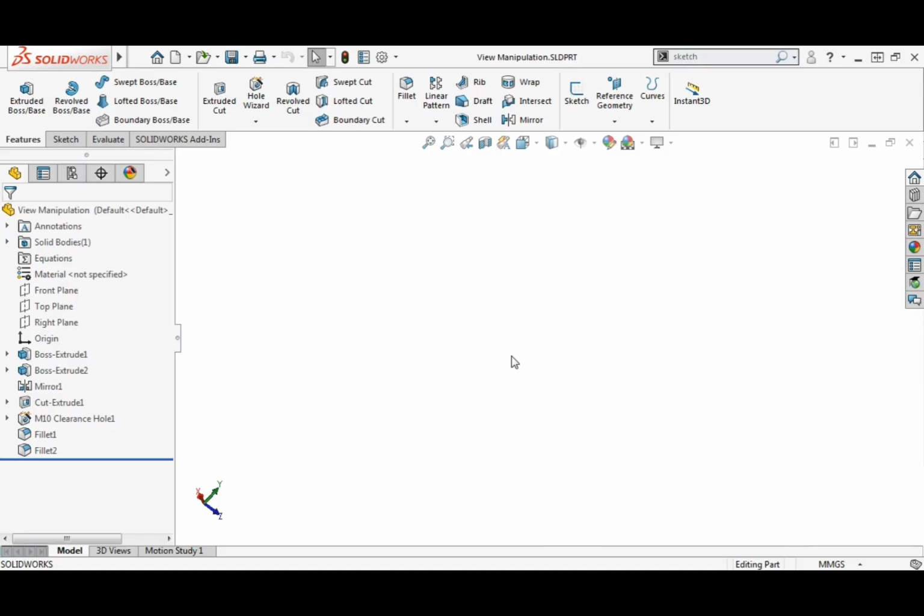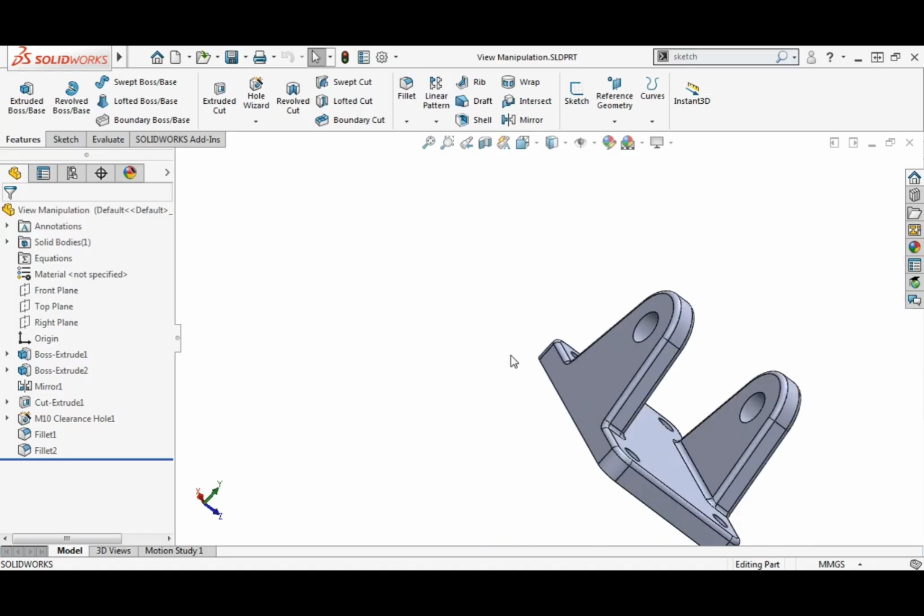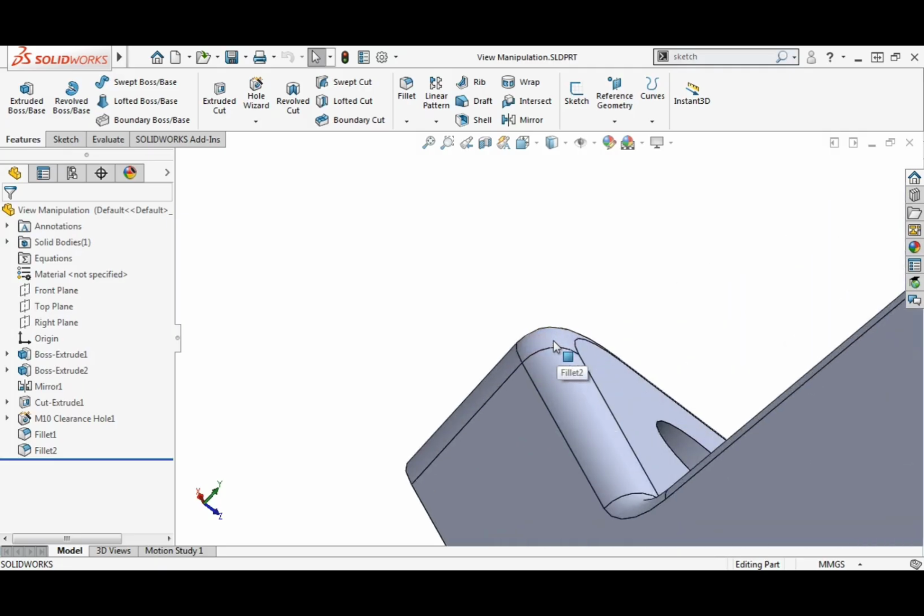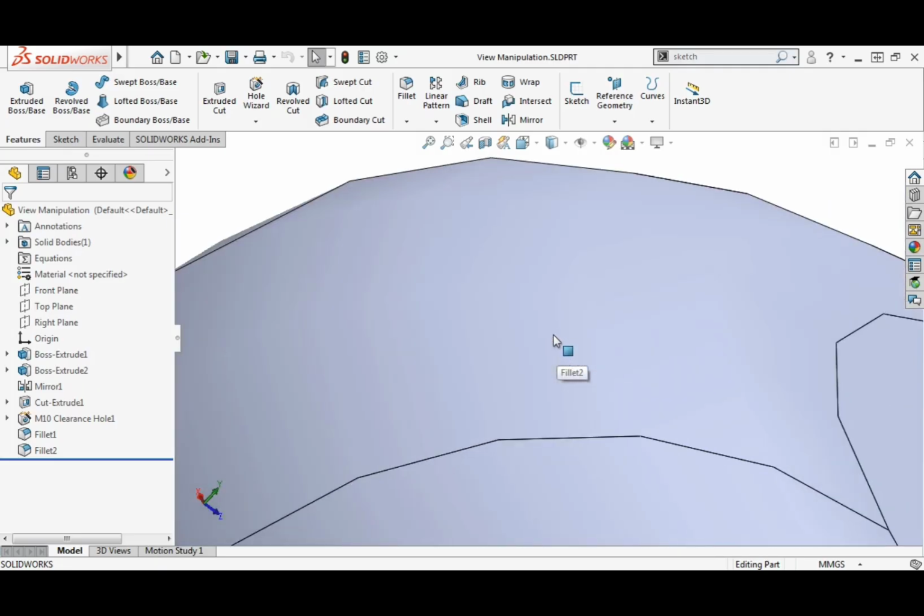This is because the mouse is positioned over the white background immediately after I start zooming in, which means I'll be zooming in on that spot in the background and not the model. If I want to keep this from happening, I must relocate the cursor to the spot I want to zoom to every few mouse wheel clicks while zooming in.